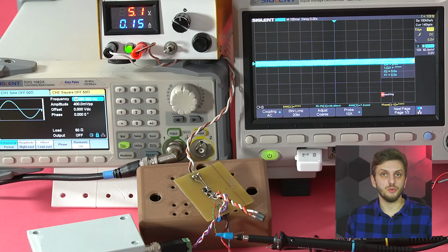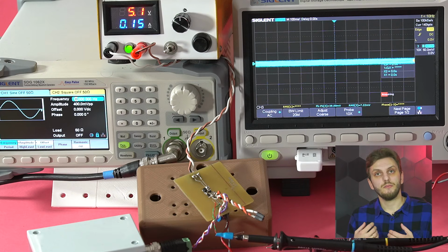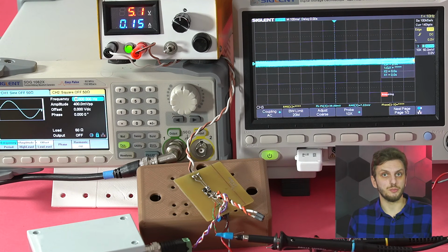Now the final thing that we can do to confirm our measurement result is to indirectly measure our crossover point by applying a load step. So when you're applying a sudden change in output current, the power supply will have to react to this, and the way in which it reacts can tell you a thing or two about your crossover point.